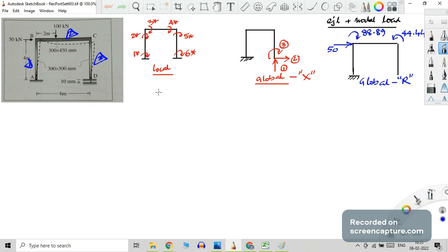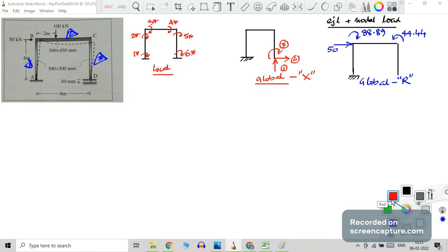And also we have the nodal loading and span loading. So nodal loading has to be taken directly, no change in direction, etc. But the equivalent joint load is the reverse of the fixed end moment. Here only moments will come, not fixed end reactions. You know that our coordinates are like that, and also you know about our local coordinates 1 star, 2 star, 3 star, 4 star, 5 star, 6 star, and you know about our element flexibility matrix corresponding to this particular local coordinate system.